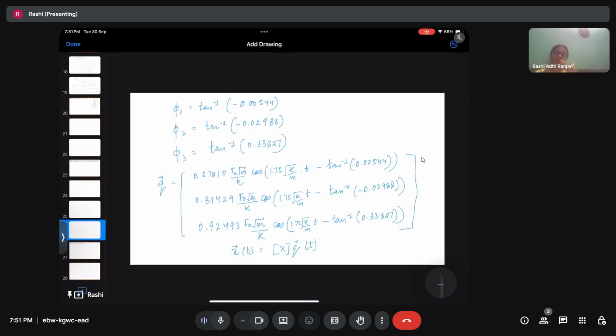But once it crosses the transient phase, the transition occurs and it is now at the steady state solution. The contribution of only the damping frequency is going to be there, right? Over here also, the damping that we have considered and then we have solved, it is the proportional damping, right? Proportional damping means C is actually proportional to the mass matrix and then it is proportional to the stiffness matrix and then we add.